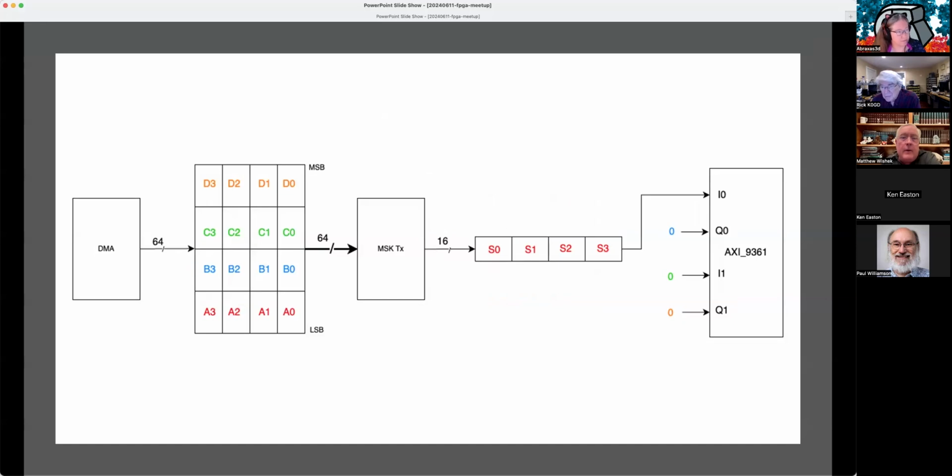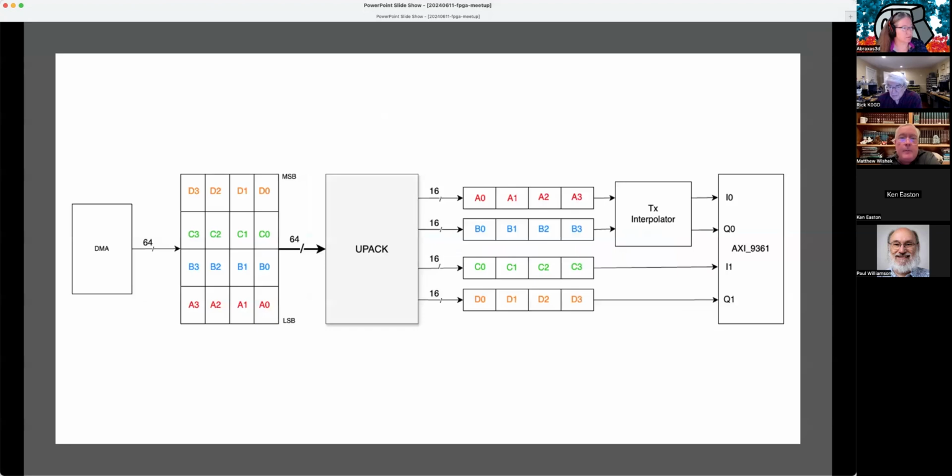So right now, I'm running a bit rate of 54,200, and an IF of 10 times that. I meant to run it 20 times. Oh, and then I'm running a sample rate of 1/8 the 61.44 megahertz. So I'm going to run some more simulations. I slowed it down just because there was some funniness happening, but I need to go back and rerun it. So there's some possibility that we'll want to put the interpolator back in, but I'm just trying to save the space if we don't need it.